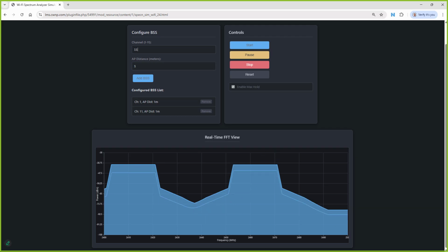But if you look in the 802.11 standard, at the spectral mask for the various different channels, you'll see that it does have these masks in the standard. And what you have is, yes, you have the channel, and then you have these signal strength fall off boundaries at the side.